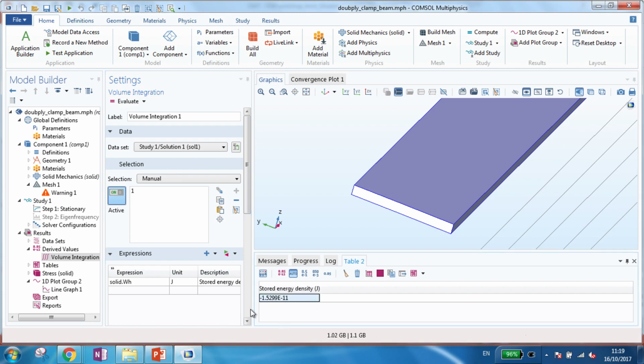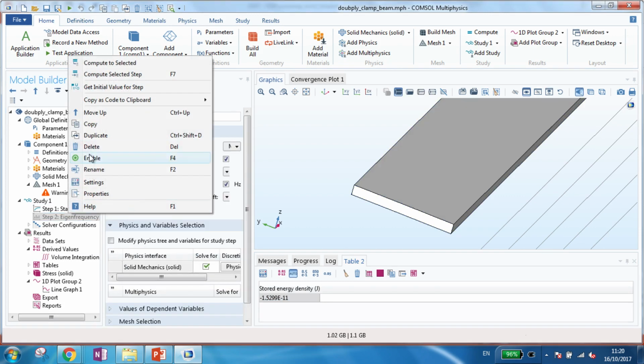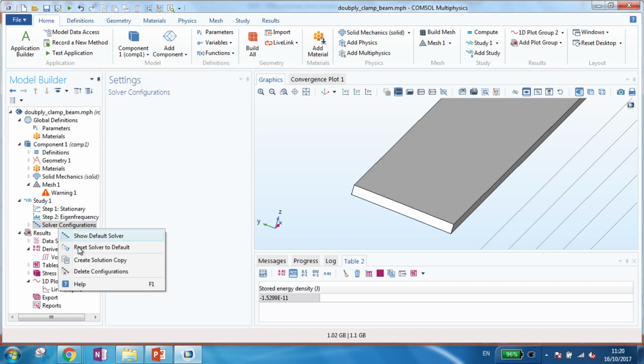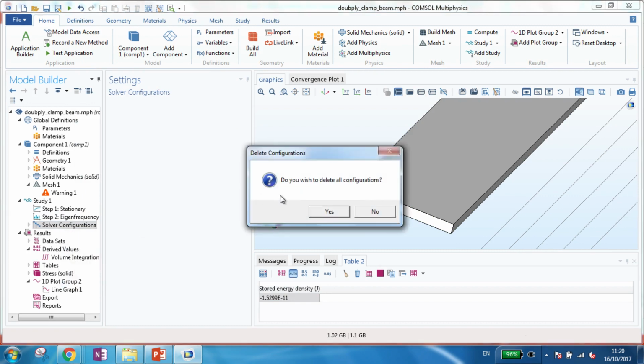And then from that point cut, you can take the displacement of any point you want and calculate the effective mass with respect to that point, normalized to the amplitude of that point. Is that clear? So that's how we calculate the effective mass, normally using the integration.